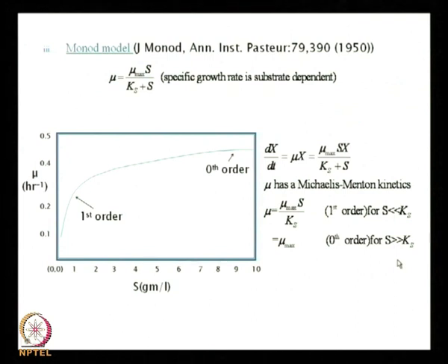Done? Okay. So, this is the Monod model, and what I want to do next, as probably the last thing today, is the modified Monod model. The modified Monod model is a slight modification of the Monod model. It is found experimentally that the rate of cell growth decreases at high values of initial substrate concentration S naught. It was a strange thing that was seen: increasing the substrate concentration is good, but if we increase it to a very high value, then instead of helping, it retards the cell growth process. And how do we include that?